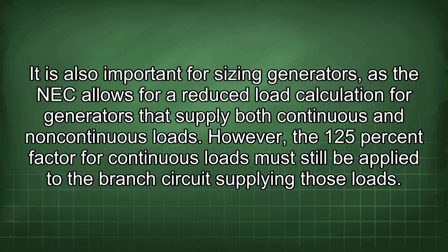It is also important for sizing generators, as the NEC allows for a reduced load calculation for generators that supply both continuous and non-continuous loads. However, the 125% factor for continuous loads must still be applied to the branch circuits supplying those loads.